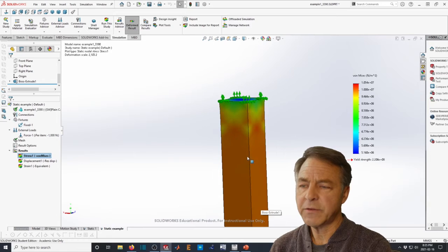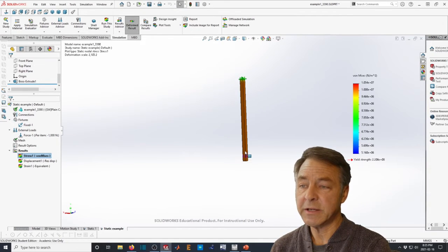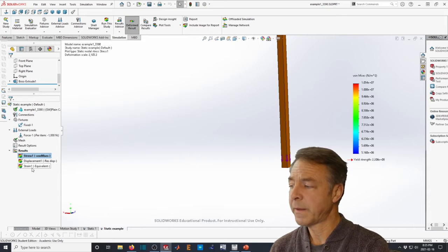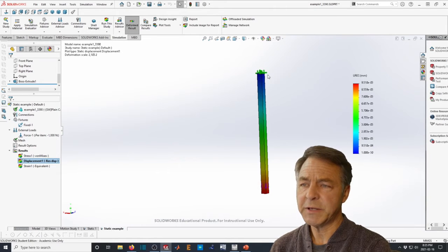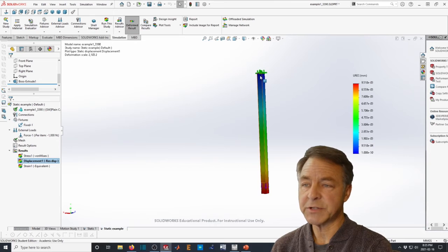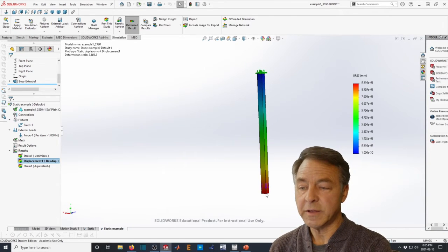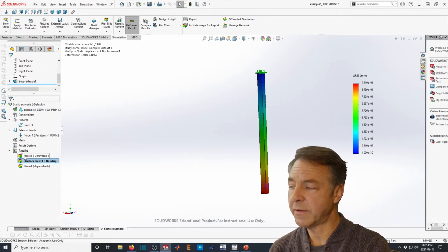So even though this was a coarse mesh, that's interestingly present. Now the other thing I can look at is the displacement. This shows in the colored plot here: blue is essentially zero displacement and red is big displacement. The bottom end was being stretched, and it's moved further than the top end.